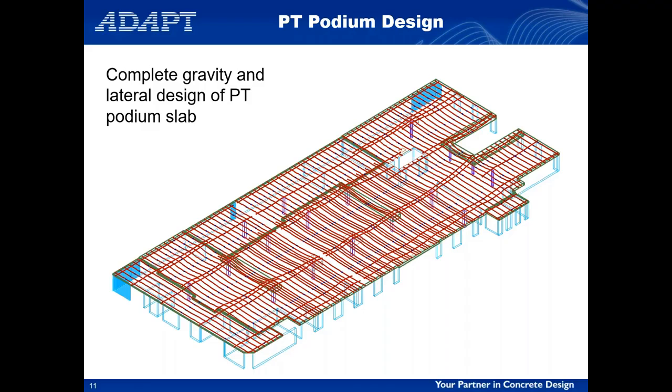So one thing you may want to consider and review in your design approach in your office is, because these podiums tend to be closer to the ground and obviously connected to the foundation, you may choose to switch the default boundary condition when you're doing the PT podium design in Floor Pro, switch that to fixed as opposed to the rigid roller. So that's just one piece of advice to think about, and you can just do a quick comparison: take one of your models, run the two and see what happens.